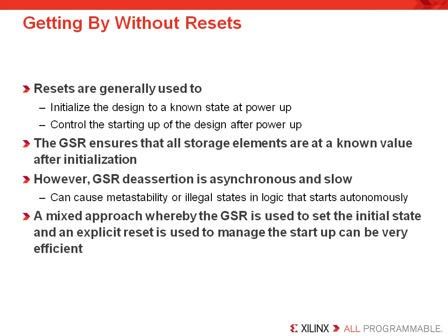You also control the starting up of the design after power up. That's another thing that you can also control at your leisure. So the more you know about configuration, the more you can actually hopefully design out any unnecessary resets in your design. The GSR ensures that all storage elements are at that known value. However, the GSR deassertion, again, is asynchronous and slow. And this is part of the reason why this is done as part of the configuration process.